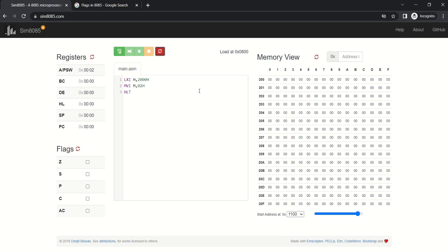And the second thing is, it will point to the memory address from which the next byte is going to be fetched, right? If my pointer is currently at memory location 2050, then the next byte will be fetched from 2051. So my program counter will point to 2051. Then if I'm executing 2051, it will point to 2052, right? So that is the work of the program counter.